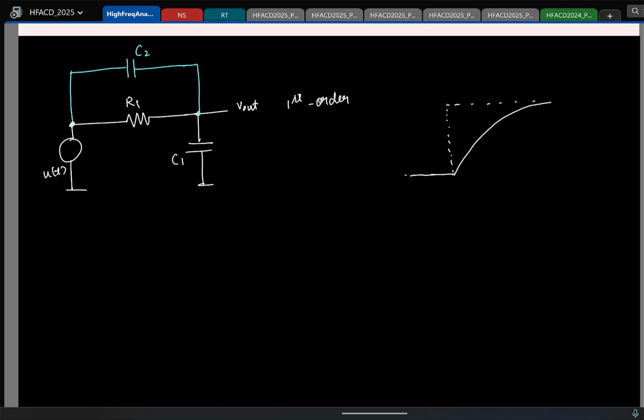Yes, because I can short this capacitor, and the output is still non-zero. Even intuitively, you see that there are two paths for the current to flow from the input to the output. One through the capacitor, one through the resistor. Both will have different frequency dependence, and at some complex frequency it can add up to 0. And you can quickly compute the 0 location.